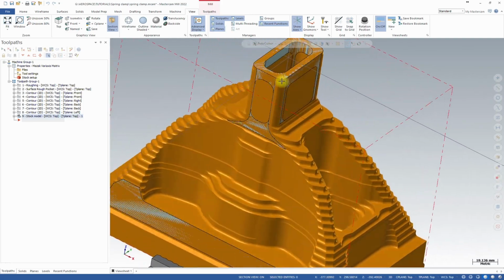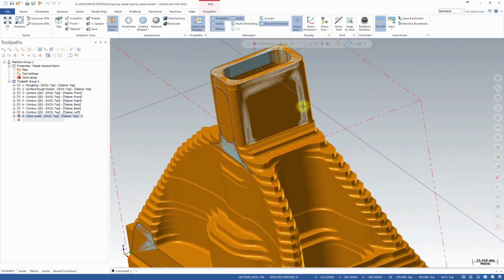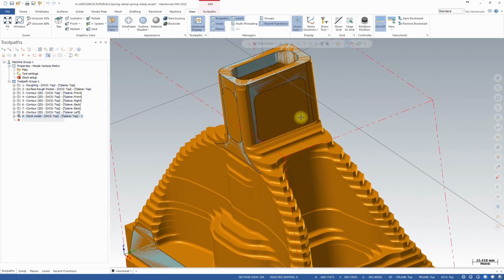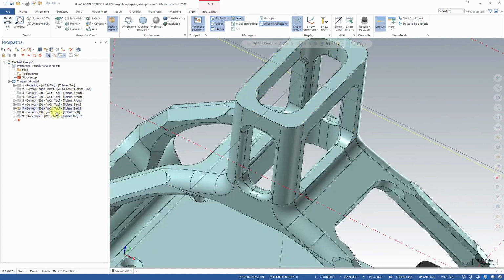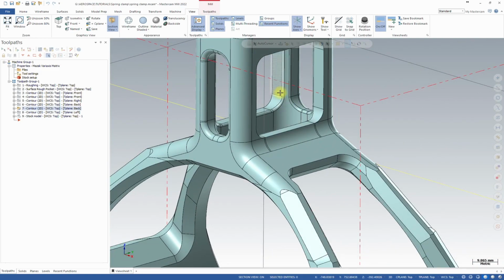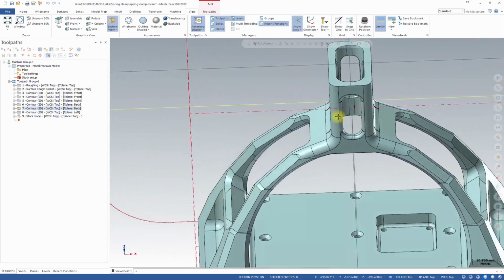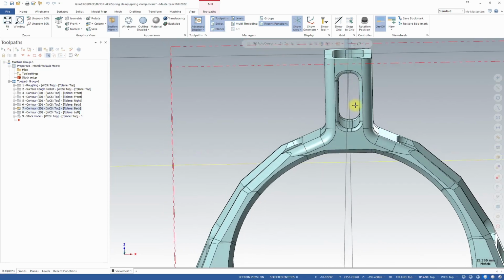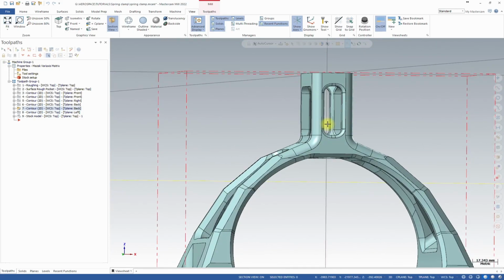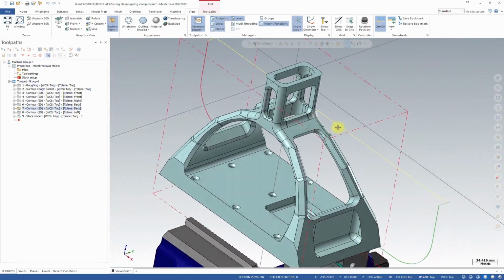Okay, so with our next toolpath, we are going to machine those cutouts. And the way I'm thinking, we're going to machine these two first, and then through those cutouts, we're going to machine those fillets inside. Okay, and then we will do the same here. We're going to machine those at the end and machine those bits inside. So yeah, let's start.